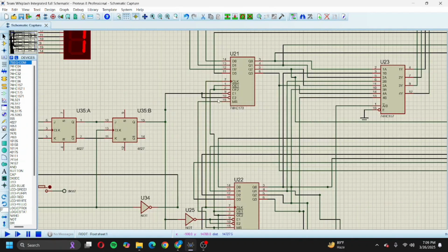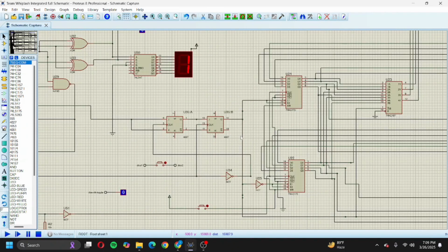And in the case of the input activation pin, because it is active low, we have connected player 1's register's input activation pin directly with the slave flip-flop's output. We have connected the inverted output of the slave flip-flop with player 2's register's input activation, so that each time the output gives 0, meaning when marks and demarks pass through player 1's present or updated position, the D flip-flop will have activated input and will pass the input to the output whenever a clock pulse is given.